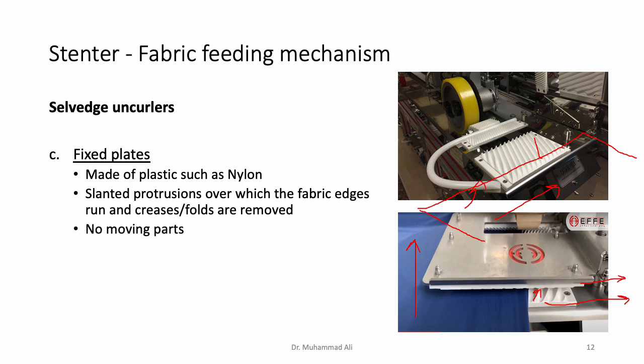Okay, as I mentioned, there are no moving parts in this type of selvage uncurler, the fixed plates, so they are in a way easy to maintain. But over time, these protrusions will wear off, and you have to replace these plates. However, there is no electricity consumption, and as such, no routine maintenance required for these fixed plates. As I just discussed, the effectiveness can be questionable.